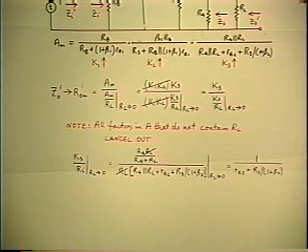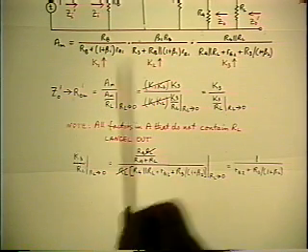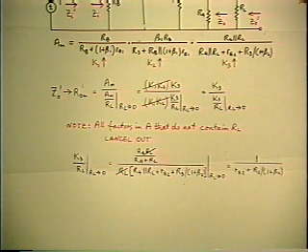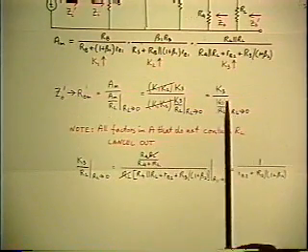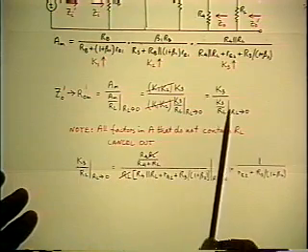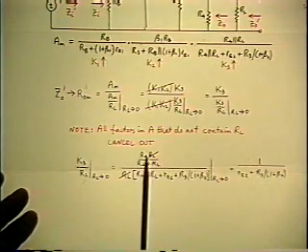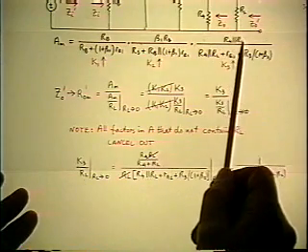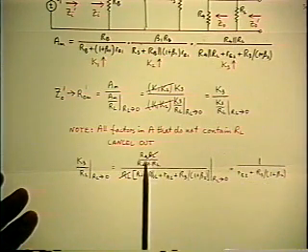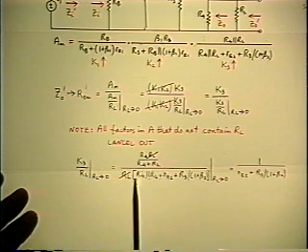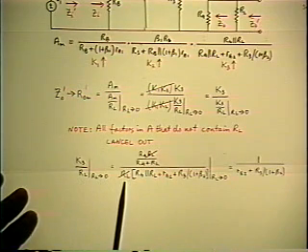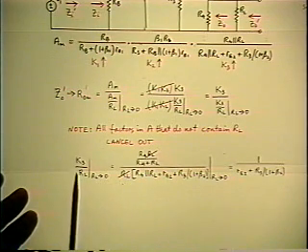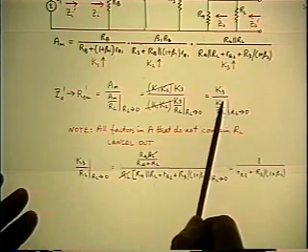Now, that always happens. So immediately, most of the stuff in the gain goes away. Okay? Well, work on what's left. Find the limit. K3 is this ratio, and in the numerator, now finally is the time to multiply out product over sum. The denominator stays the same. We have to divide it by RL, and then the RL that we're dividing into it cancels the RL that's inside the K3.